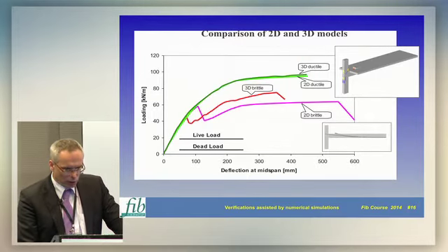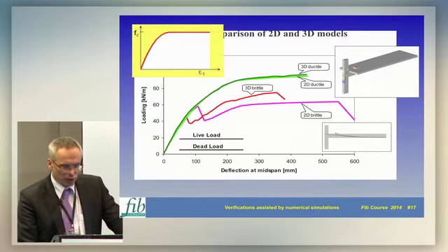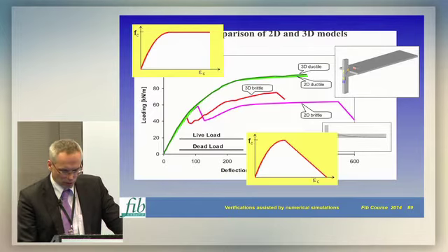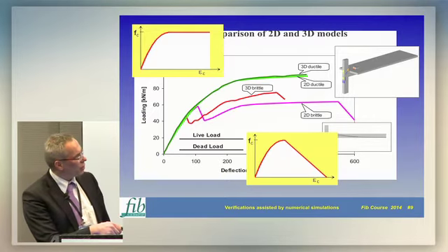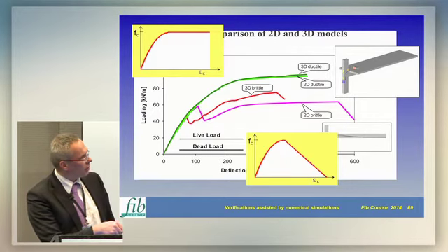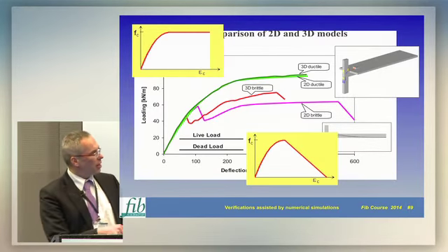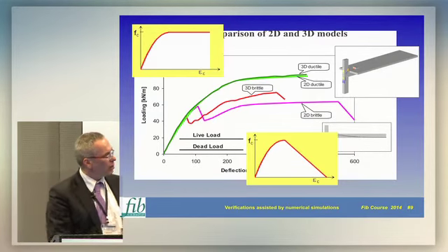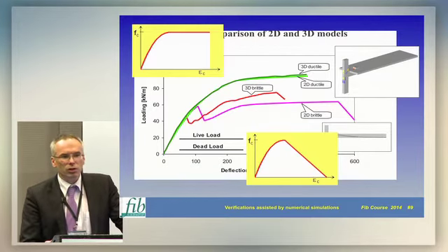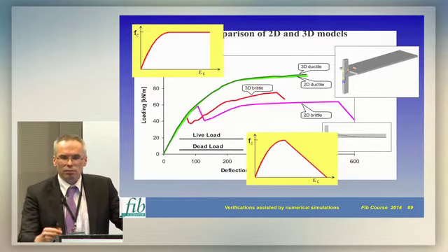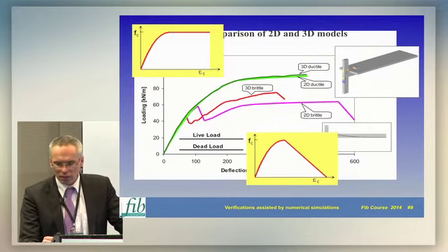And in addition to the serviceability limit states, the ultimate limit states were also checked by nonlinear analysis. In this case we investigated, by making a parametric study, what the ductility would be in these regions. Because, of course, the model that we are using is a 3D model for concrete, which considers the triaxial state of stress, also the confinement.